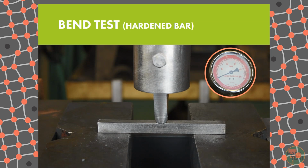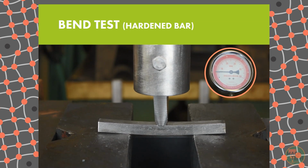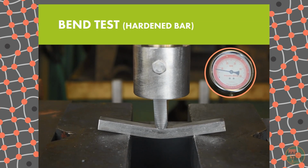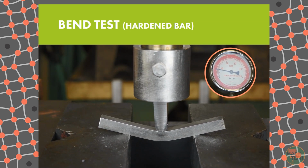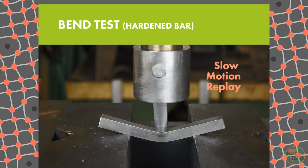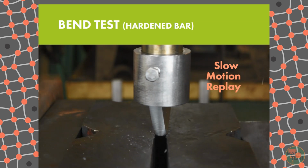Let's try another one. This is a piece from the same bar, but this time I hardened it. Watch what happens. It takes twice as much pressure to bend the bar, but when that fracture on the bottom opens up, it's only for a second before the material snaps in half, releases all that energy, and goes flying across the shop. Let's watch that again in slow motion. Whoa, I'm glad I was behind a plastic shield for this one. Well, I think the experiment matched our expectations for how softer versus harder materials behave.